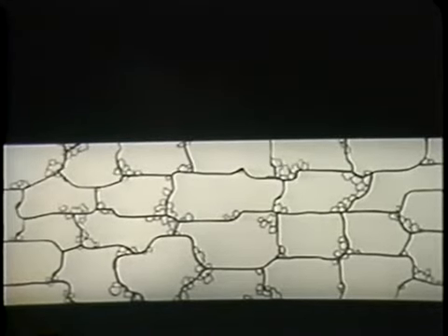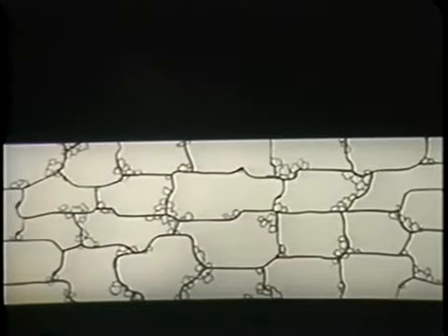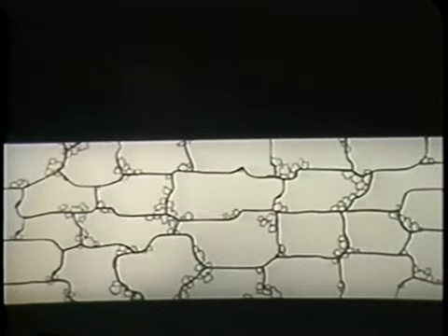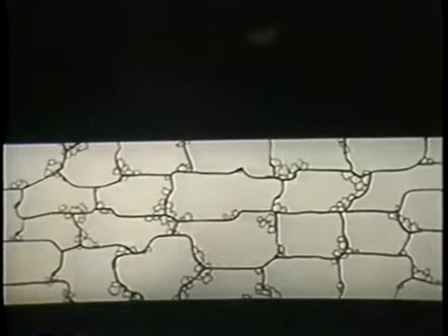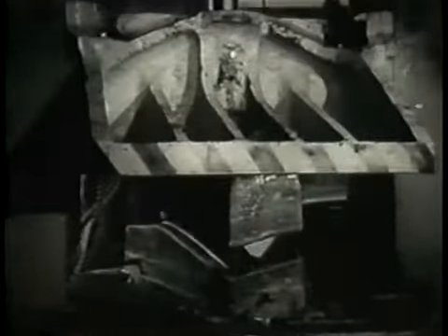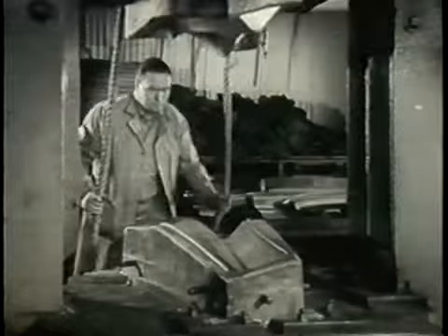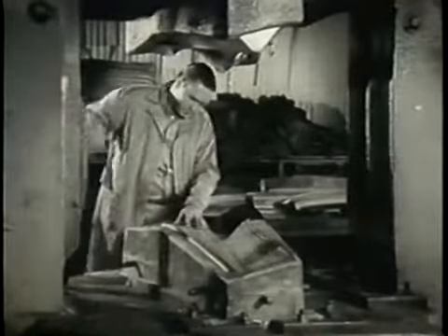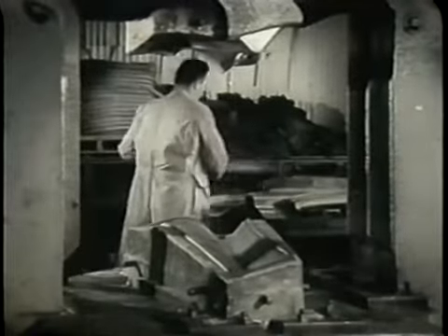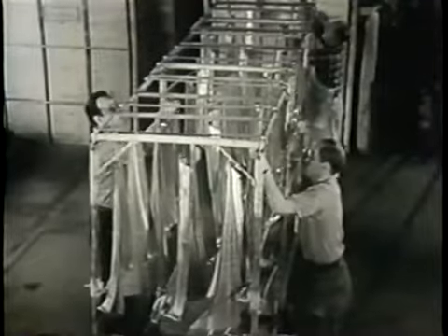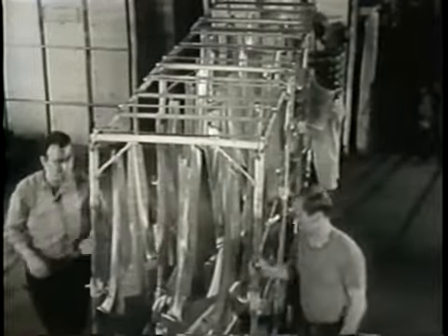The cold working involved in the hammering, hydropress forming, drop hammering, and deep drawing operations results in grain rotation and elongation. But since the plastic deformation is generally more severe, fragmentation and crushing of the grains also occur. The fact that severe cold working results from such operations as drop hammering and deep drawing gives rise to the need for an annealing or softening process between blows or other forming operations in order to prevent rupture of the parts.